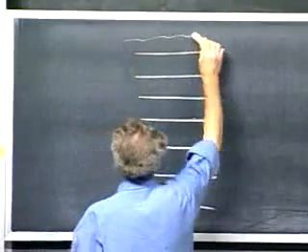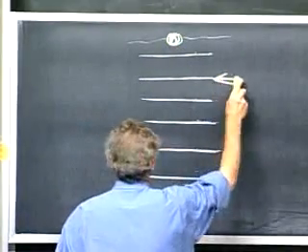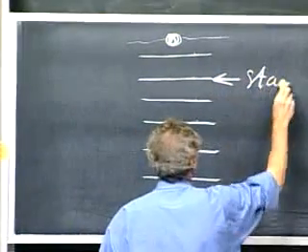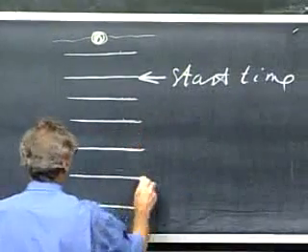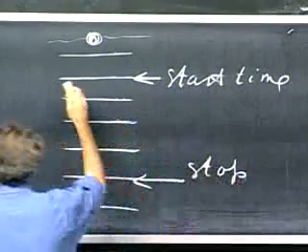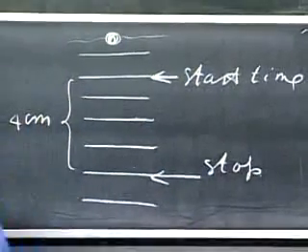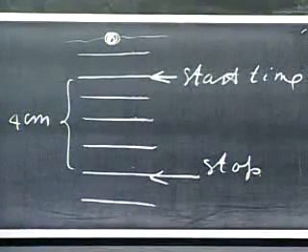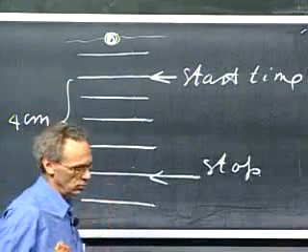So here is the liquid, and the ball bearings are dropped from above. When it reaches this line, I will start my timer. And when it crosses 1, 2, 3, 4, when it crosses this line, I will stop my timer. Each mark is about 1 centimeter apart, so this is a journey of about 4 centimeters. And we will measure the time that it takes to go from here to here.